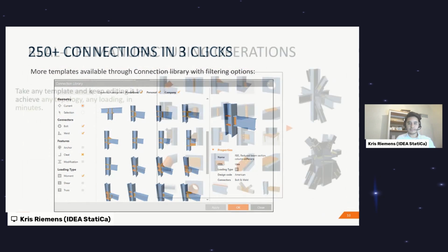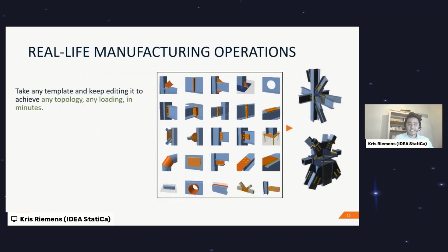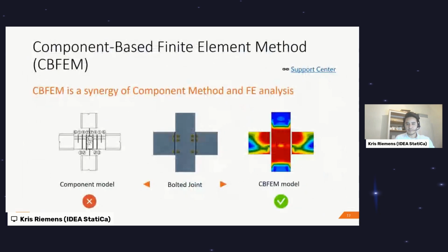To design your connection in the connection application, we offer many different so-called operations. These operations to modify the connection in IDEA StatiCa mimic the real manufacturing operations actually. You can either start with a predefined template or start from scratch. And by using these operations, one can keep editing the connection to achieve any design in minutes.